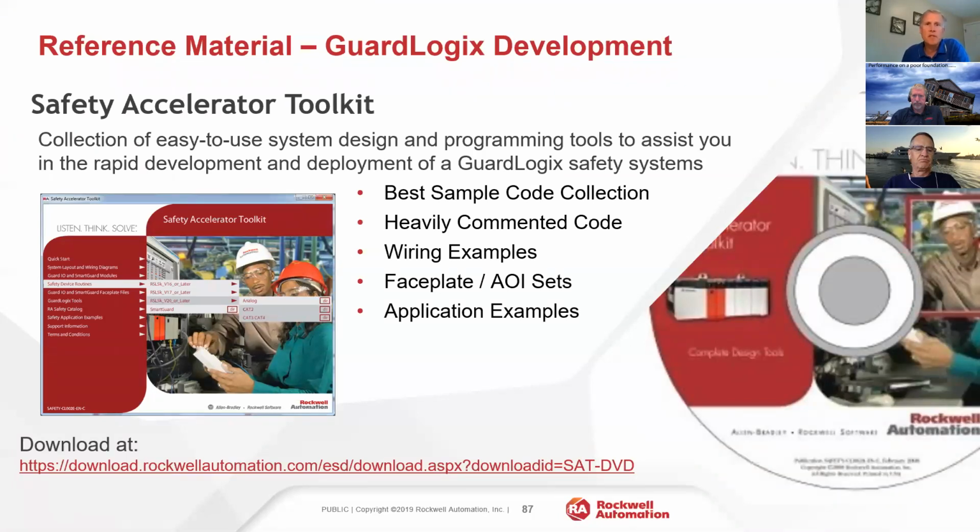So we mentioned safety PLCs, and we will be talking a little more on the hardware and software solution products in our next section. I do want to talk a little about the Safety Accelerator Toolkit, which is available for our GuardLogix PLCs. It is a collection of easy-to-use system designs. It has programming tools, and it will assist you in developing and deploying a GuardLogix safety system. It offers simple code that is heavily commented. There are wiring examples, faceplates. They go through some application examples, etc. The Safety Accelerator Toolkit is a great tool to be aware of.